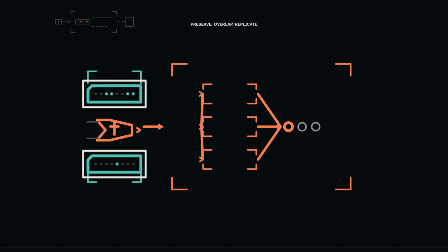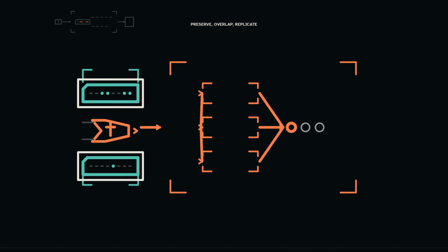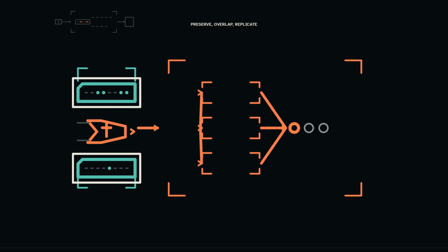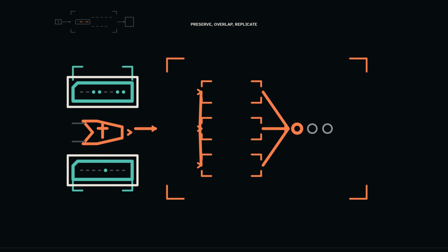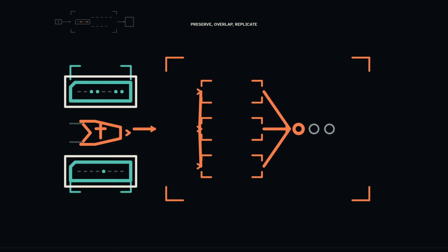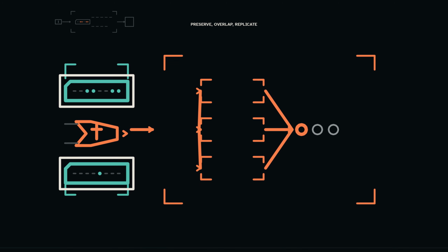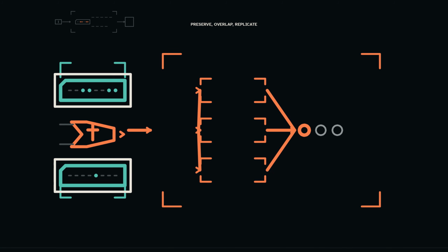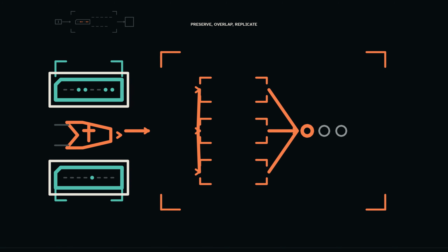A wider processor may inspect several waiting instructions and execute a later independent operation while an earlier one waits for data. This is out-of-order execution. The phrase describes internal scheduling, not permission for later instructions to rewrite the program's meaning. The processor tracks operands, dependencies, destinations, and possible exceptions. Work may finish internally in a different order, yet architectural results must become visible according to the machine's retirement and memory ordering rules.